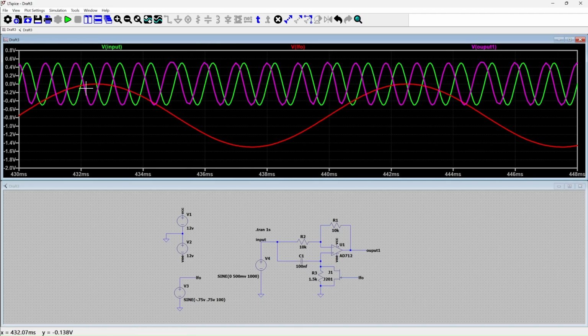You can see when the VGS is becoming 0, the phase difference here is quite large. At this point of time, this JFET has become a perfect short, and that's the reason why the resistance has reduced here. And when this VGS goes down and touches low voltage, then this acts as an open circuit, and the entire resistor is appearing across this terminal, and hence the phase difference here is different.